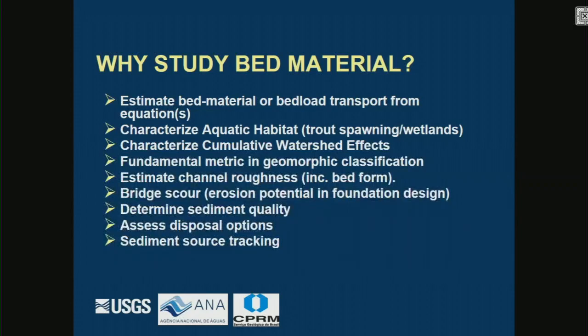And if you have your suspended sediment sample and your bed load sample as physical measurements, then you can look at how your model is doing compared to what you actually measured in the stream. That's kind of how I think of these as different. The bed material is the input to the model, and the suspended sample and the bed load sample are the verification of how your model is doing.